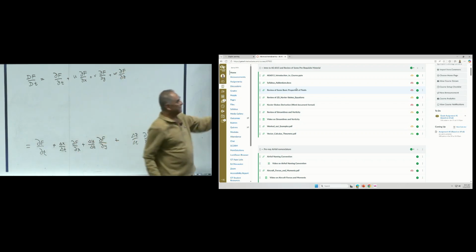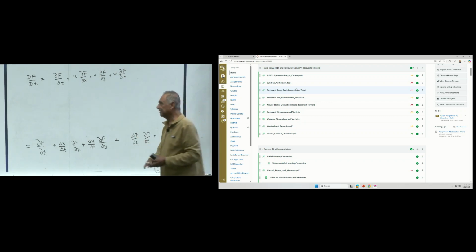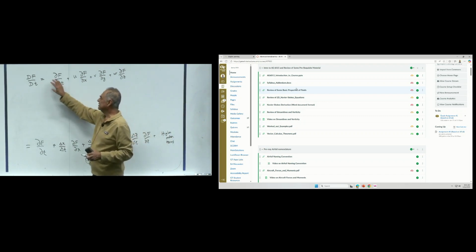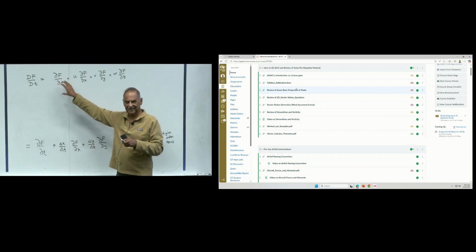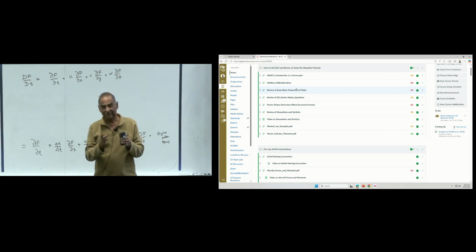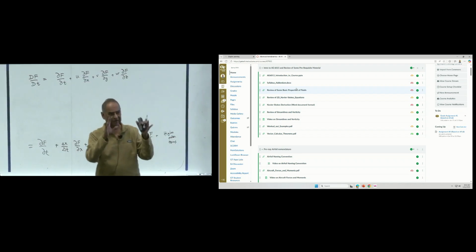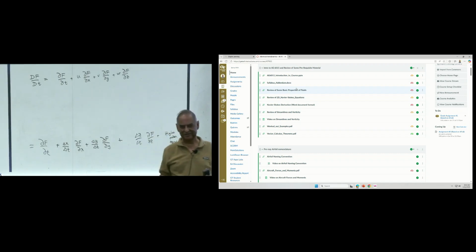So if you look at the Navier-Stokes equations that I am not going to derive, if you open it up, you'll see the rate of change of momentum will be made of this term, ∂u/∂t, plus u times ∂u/∂x, v times ∂u/∂y, w times ∂u/∂z. So what they are doing is, they are doing it in a Eulerian coordinate system, but what really happened in a Lagrangian frame of reference, how things have changed.